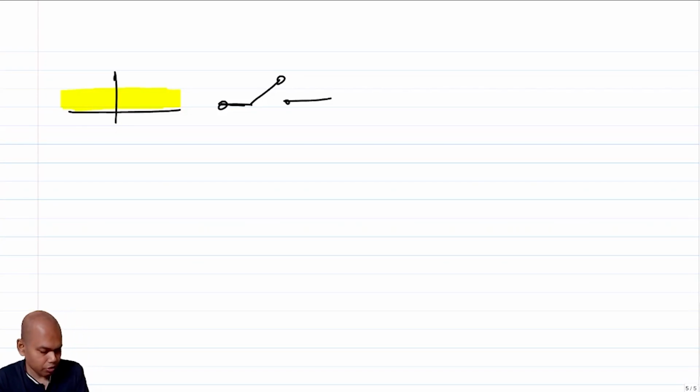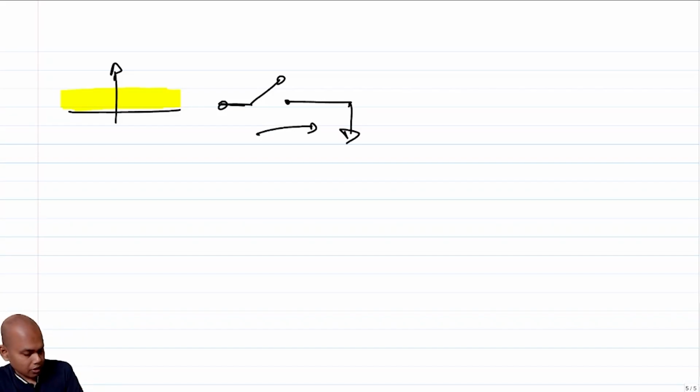So my question to you will be, let's for the time being assume that this side is shorted for the purpose of discussion. Let's assume this is shorted, right? So my question is, what will be the noise current flowing into the short circuit? Right? So this is F, and this is switching at FLO. Correct? So how should I go about thinking about it? Just like if it were a signal, what would we have done?